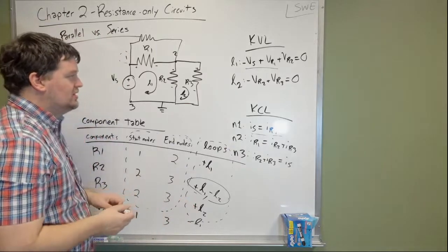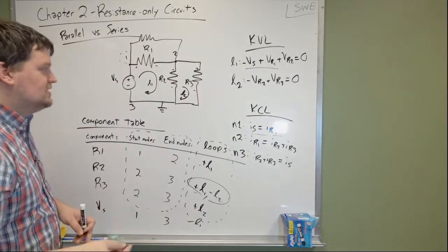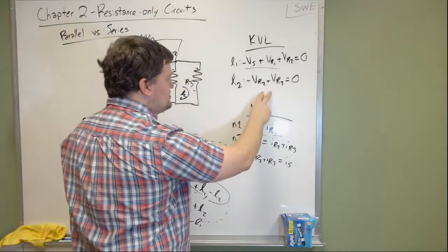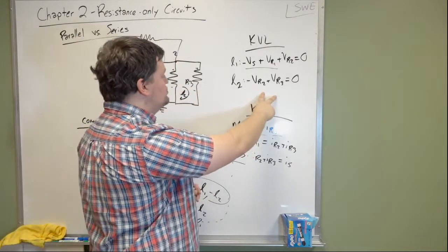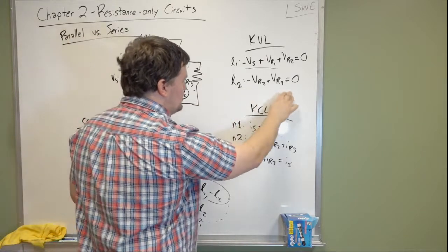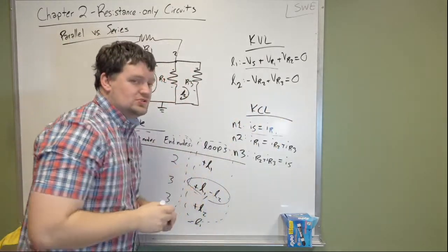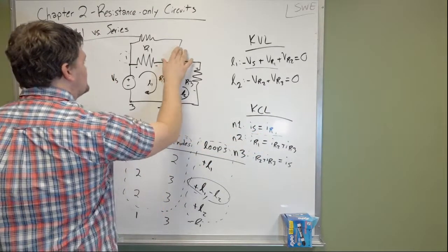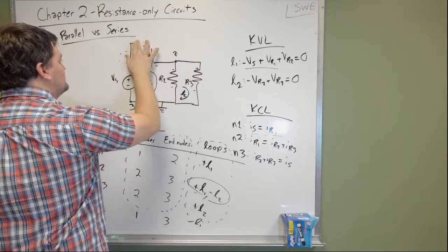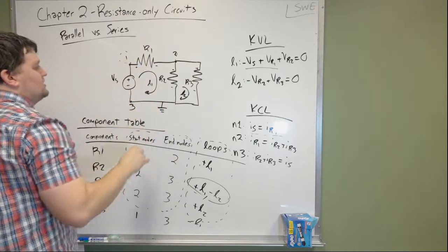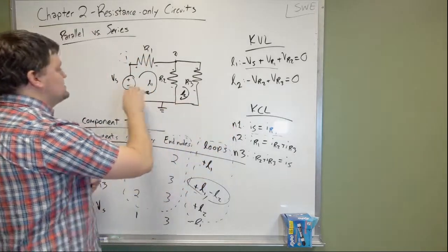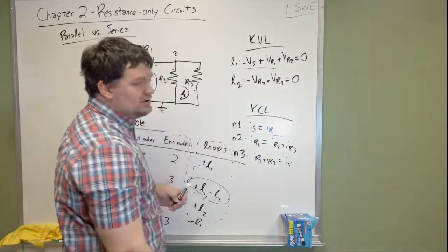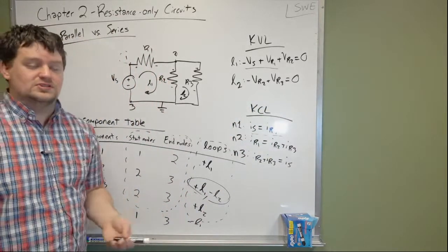and it's one of the most critical aspects of this entire circuit. The flip end of this is because these are in parallel, we end up with this relationship right here. We have one loop equation that says both of these have the same voltage. So here, these two components are in series. I'm going to erase my addition. These two components are in series, which means they have the same current. These two components are in parallel, which means they have the same voltage.